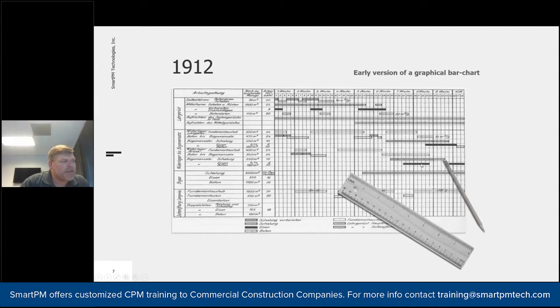You can see right here, the darkest line item here is what we deem as the longest path, which is what is actually highlighted in these critical path method programs. So even before the technology was available, our brains function when thinking about building a project in a manner that sort of lays it out in order over time with some dependencies, certain things that need to happen before others can. The CPM scheduling program is no different than that.